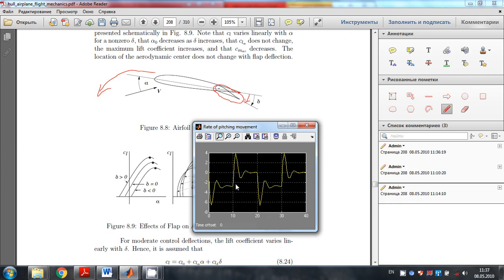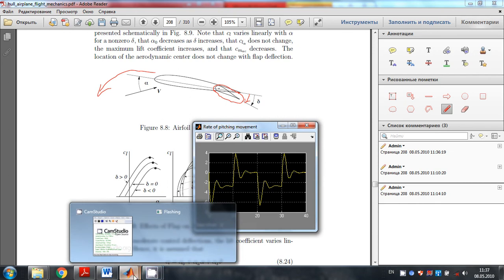So again, the whole aircraft behaves as a big pendulum. The elevator moment tries to deflect the aircraft, to change the attitude of the aircraft in the pitch. But the whole aircraft body is designed so that some stabilizing forces appear and start acting on the aircraft body. So this pitching moment doesn't get uncontrolled, doesn't get out of control. We can talk about these oscillograms more, but this is basically it.